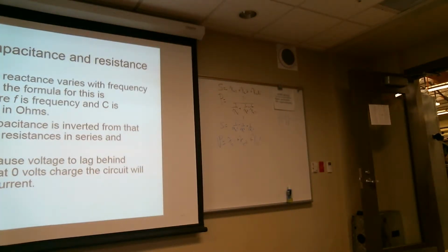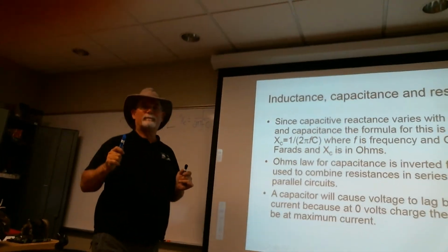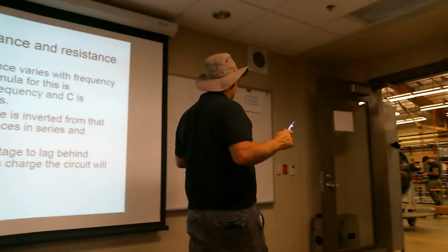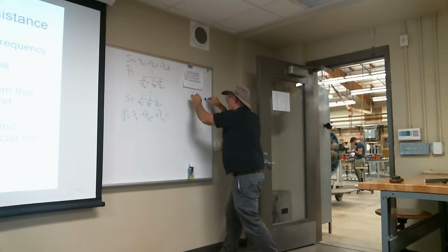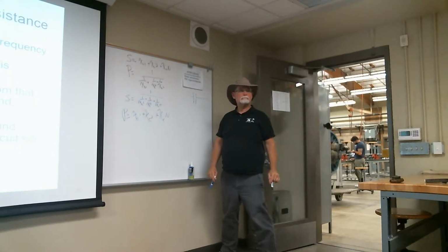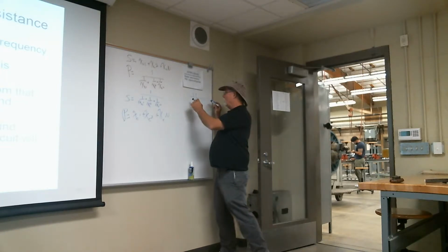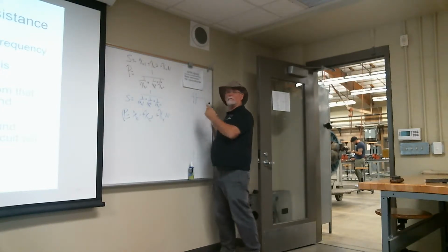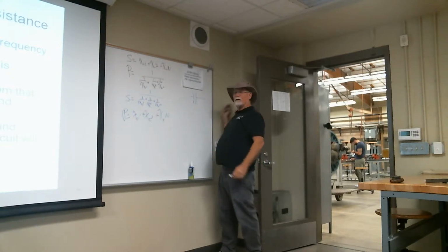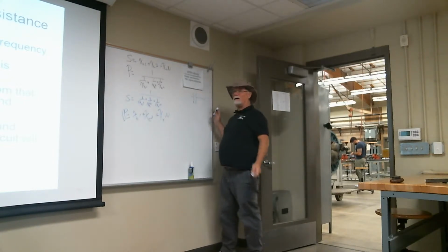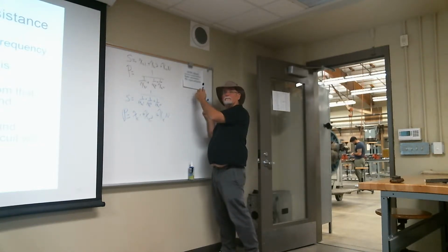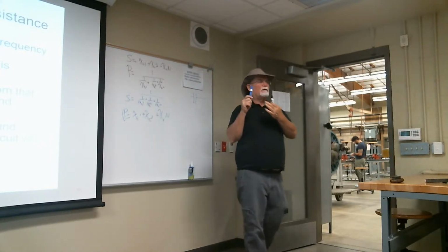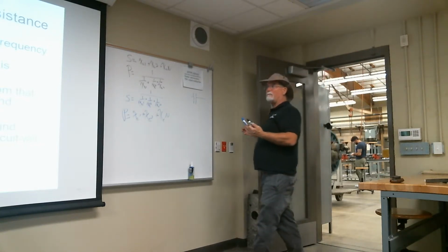Now, the other thing that's going to happen is I am the human voltage source. I'm going to take and attach my voltage to here. What's going to happen? Current is just instantly going to start moving into this thing. Electrons are going to come ripping out of here. Current's going to start coming into here. And the voltage will stay low and start ramping up. It takes a while to start ramping up. So current will be instantaneous, and voltage will take a while to ramp up.